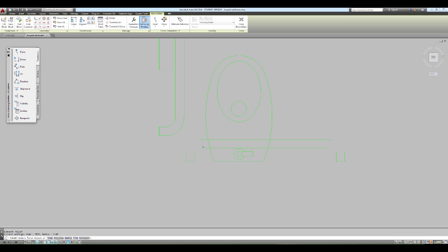Fillet with a radius, same radius that I had before. Alright, and then we're going to use offset, and that had a radius of 2. And trim. And we'll trim those off. Hard to trim them without zooming up to them. It's much easier to zoom up.